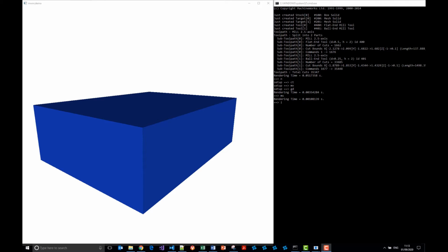For more accurate in-depth analysis, it can be useful to use MachineWorks' unique polygonal BREP Boolean engine to create watertight solids of the gouge and rest material by subtracting the in-process stock from the design part and vice versa. So in this short demo, we'll show you both of these methods and also how licensees of MachineWorks can now use Polygonica's offsetting to reduce noise and produce a cleaner result when creating solids of gouges and rest material.